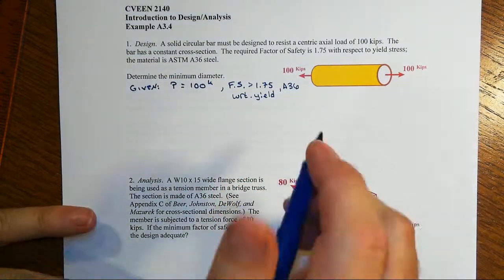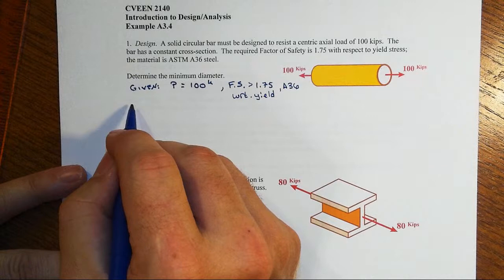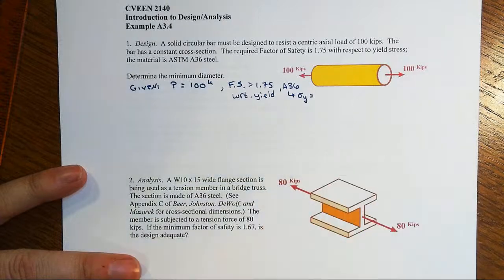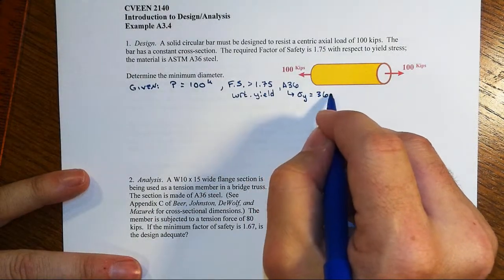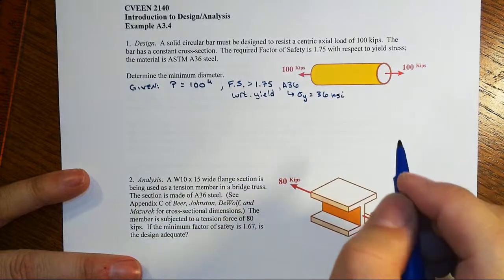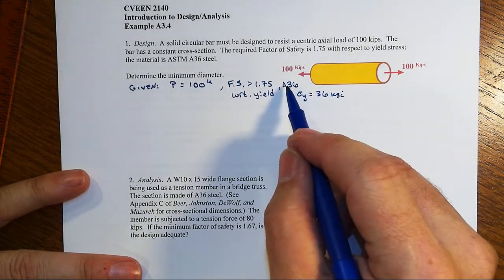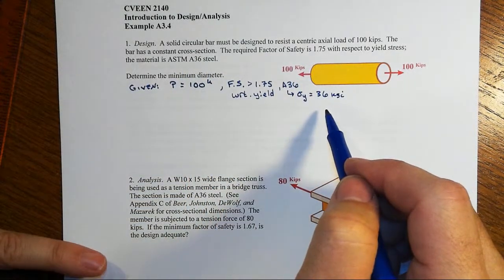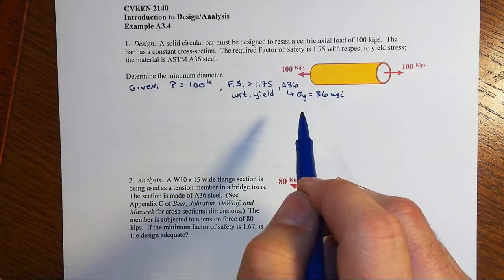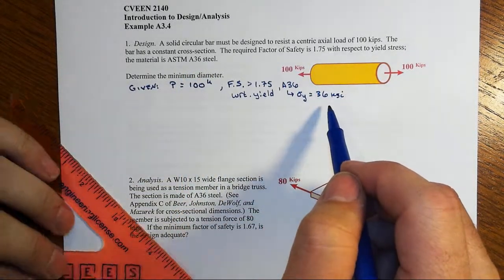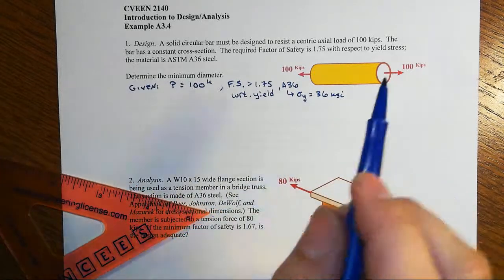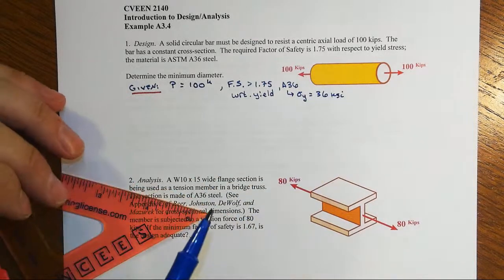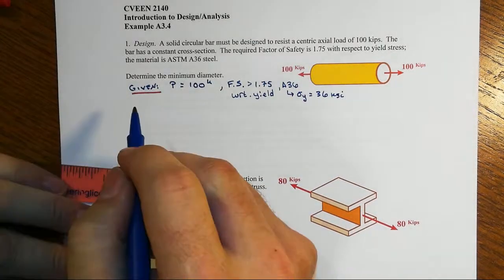Now, when you go look up A36 steel, you're going to find out that A36 steel has a yield stress value that we take for calculations to be 36 KSI, and that was intentionally chosen in that instance to be the same. It isn't always that way. This is an ASTM designation, and these numbers don't have to correspond to the yield stress, but it does in this instance. So if you have some other material, you just got to go look up what value we tend to use. We'll talk later on in another instance about when you do the test and you get those values and it's not one number, how do you decide what number is going to be used?